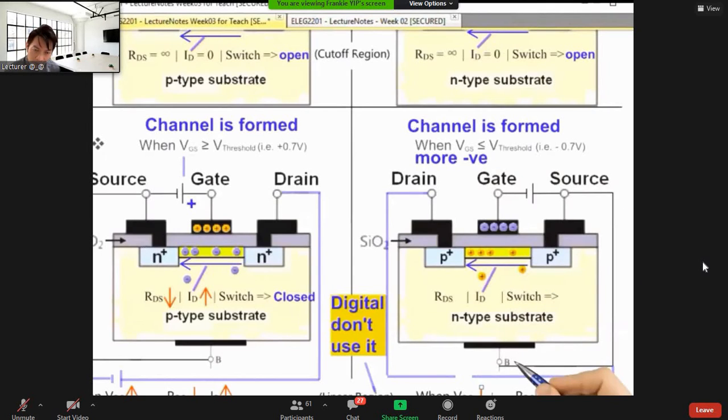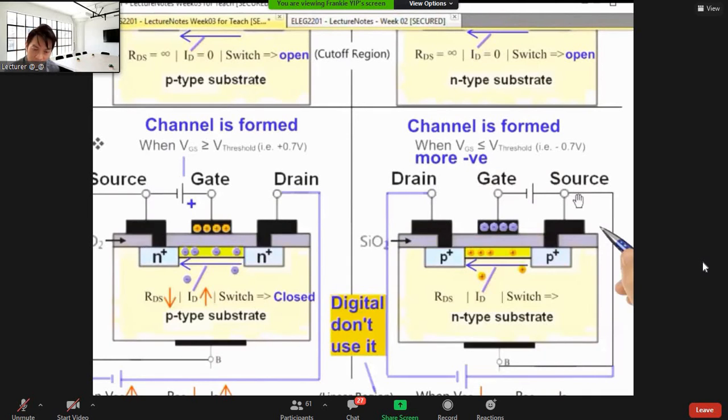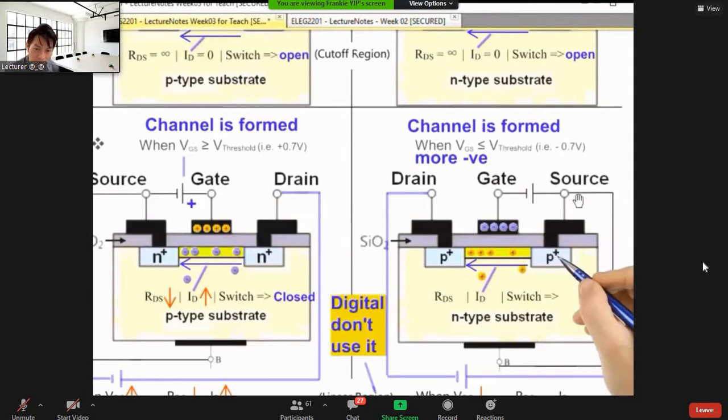So when I connect the source to the positive and the drain to the negative based on the power source, the current will pass through from source to the drain. Remember, the current path is reversed. Just now in the NMOS, it's drain to the source, right? But now it's from source to the drain. Got it? Source to the drain.